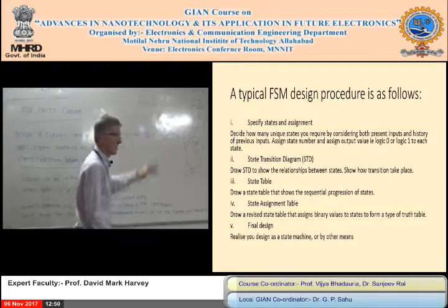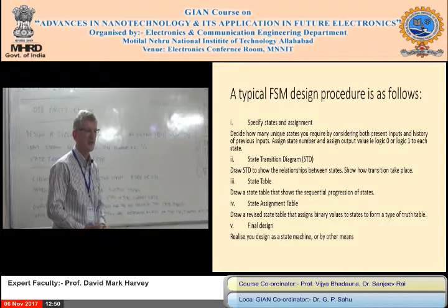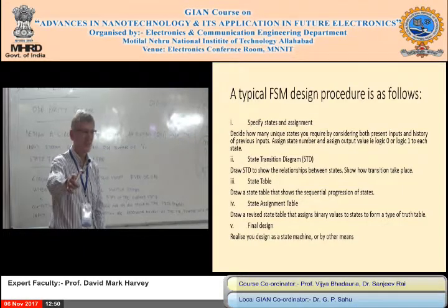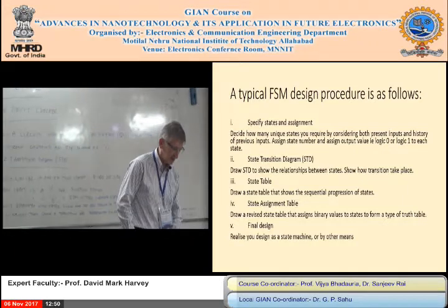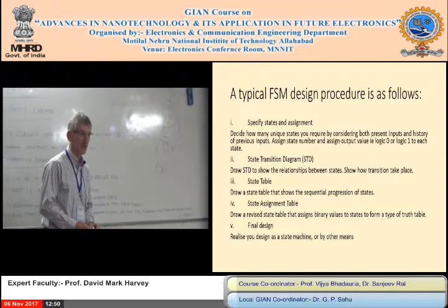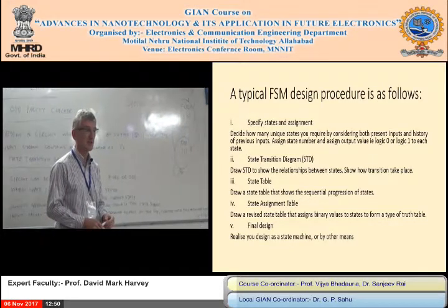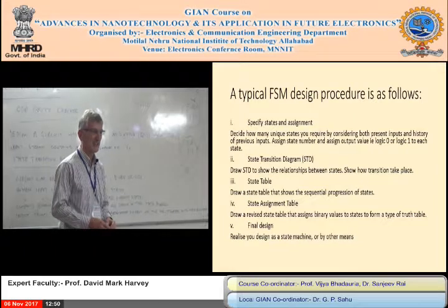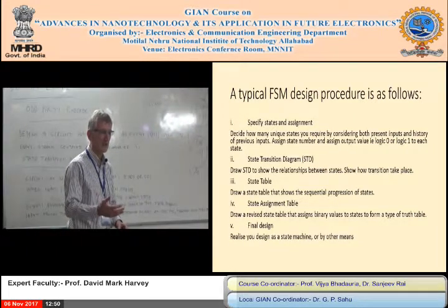So one thing is missing from that design now. Anybody any idea what's missing? Start. Well done. A company, I can't say the name because it's an unknown semiconductor company, once made a very big chip and forgot to put a reset input on it. You can't reset to a known condition. You don't know where you're starting from.